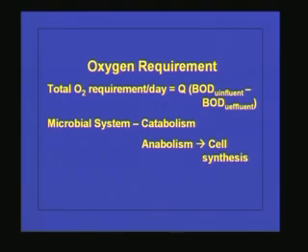So why is oxygen required in a biological process? The process itself is like that. The microorganisms are utilizing the organic matter present in the wastewater. Because of the air supply, the organic matter is getting oxidized to carbon dioxide and water, and more new cells will be generated. So the oxygen consumption rate is much more than what can be obtained by natural replenishment, because the system is open to the atmosphere.